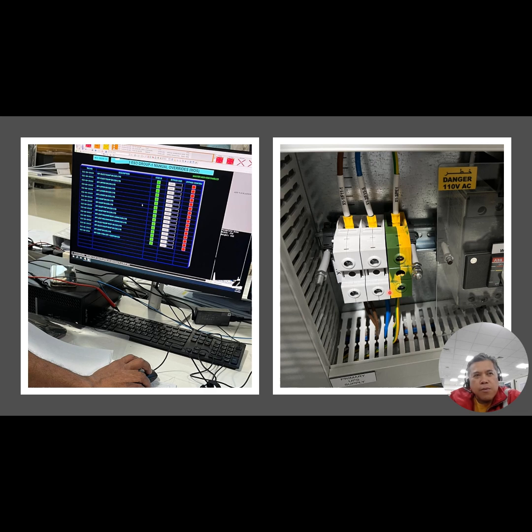That is based on our specification, design and safety information to be carried out during the FAT. The test certificates must be available during the FAT as well. Any materials and devices you need to verify as part of the bill of materials, all the components to be checked, and test procedures are recorded, because they will be the reference during the SAT activities.